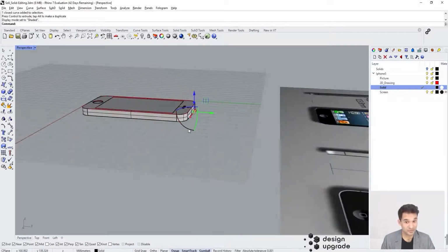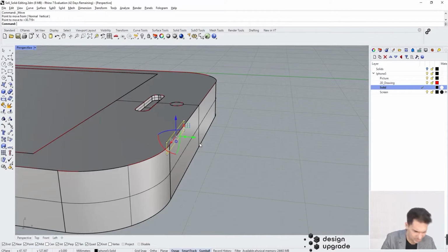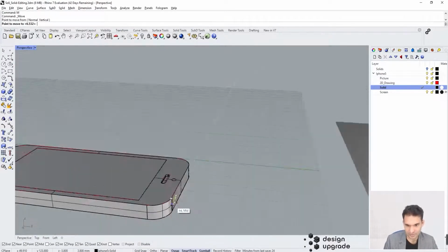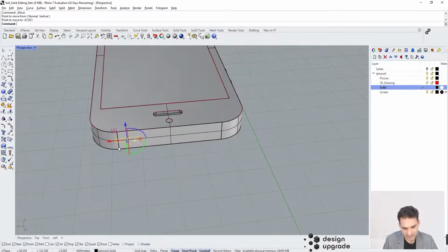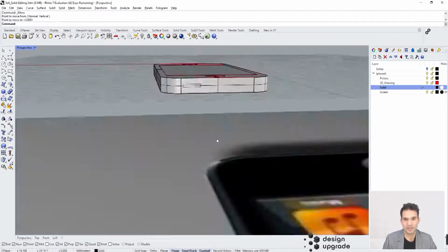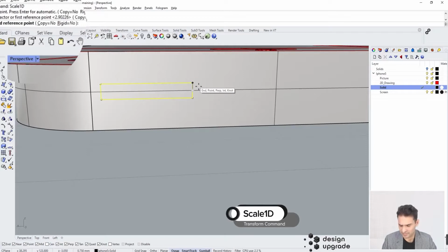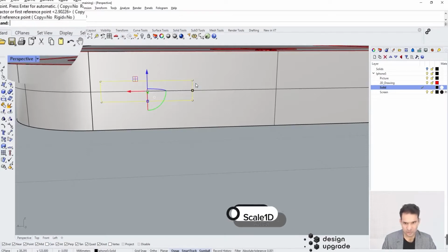I hope it's not too fast. 90. Now I want to project this the way here, move it. Let me see. It's pretty much centered actually, so let me just center it with moving it downwards until here. And I don't like this detail actually. Let me just move it all the way here, and then just 1 centimeter inside, so -1, like this. Should be fine. Let's look at this guy again, and let's say scale 1D, and let's give this 1 at least. So it's 2 millimeters.